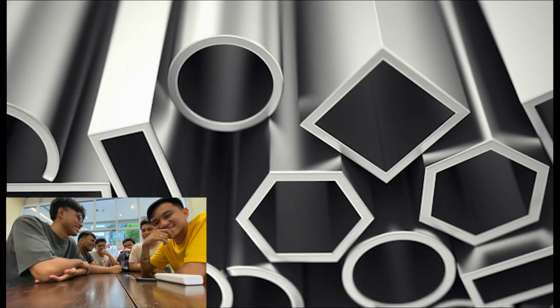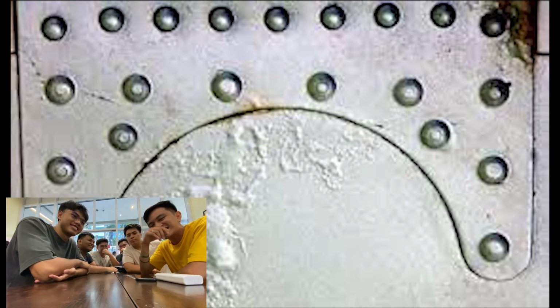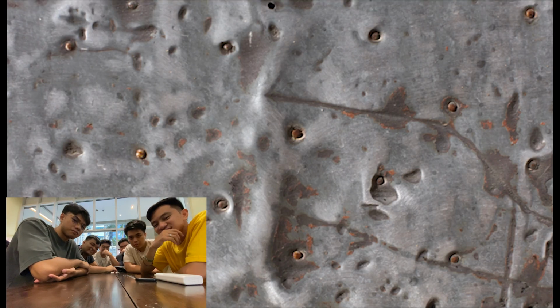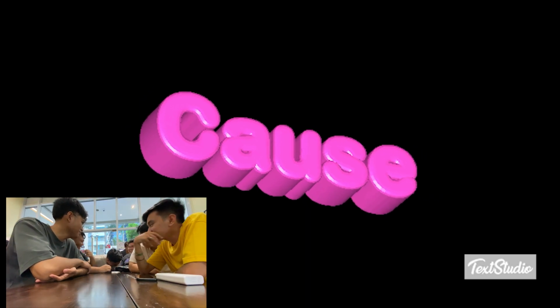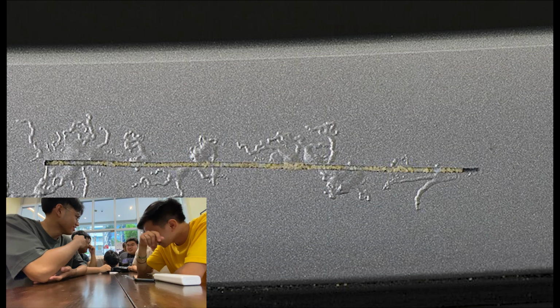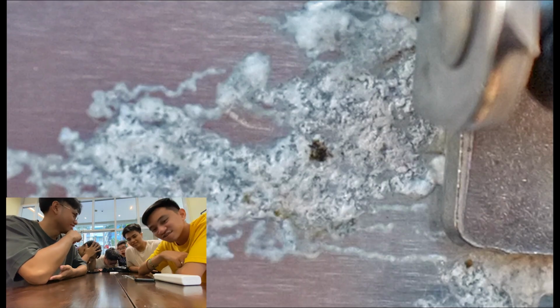7th, filiform corrosion. Filiform corrosion is a form of corrosion specific to painted steel, aluminum, and magnesium surfaces. It results in a detachment of the coating from its metallic support, which is caused by the surface corrosion of the underlying metal at the metal coating interface. Causes. This type of corrosion typically occurs on coated surfaces, when moisture or a corrosive solution penetrates through the defective coatings. It is caused by active galvanic cells across the metal surface.